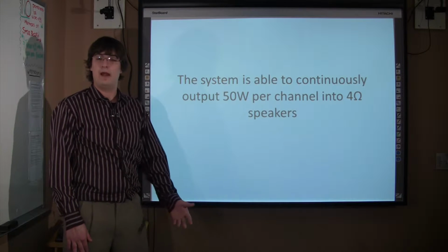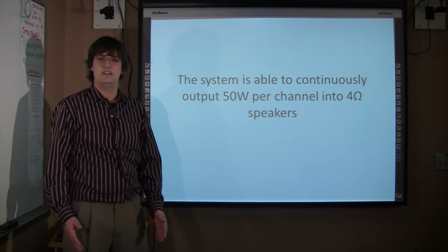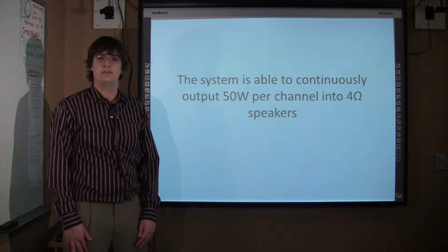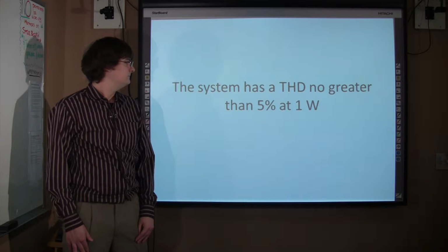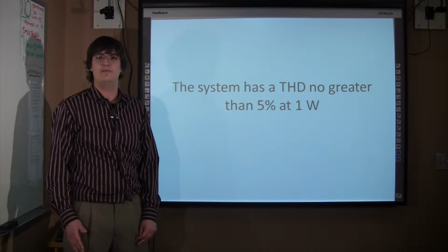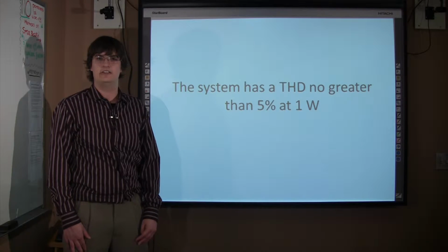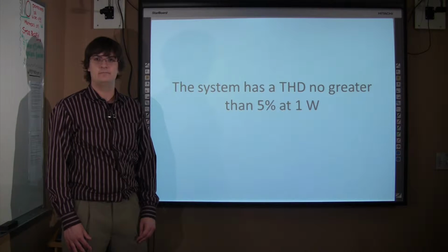The system must be powerful enough to drive 4 ohm speakers at 50 watts continuously into 5 channels. This requirement was passed. The system must have a total harmonic distortion rating of less than 5% at 1 watt to maintain audio signal integrity. This requirement was passed.